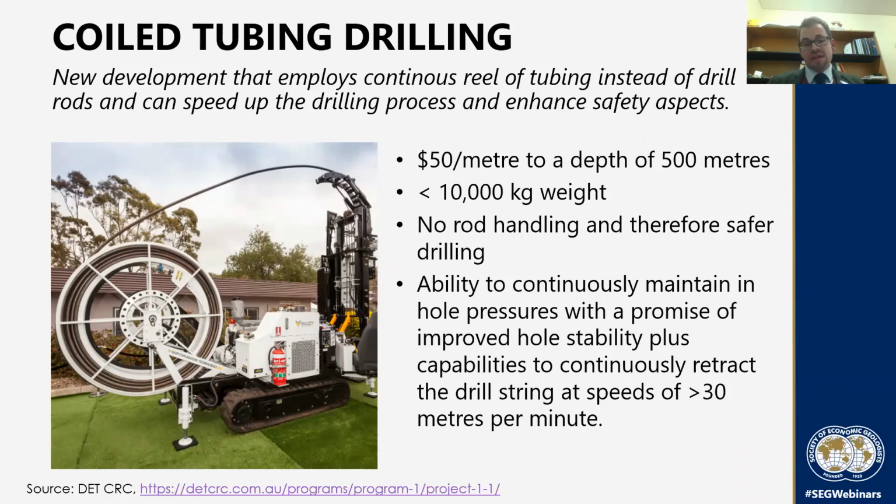I've myself never used this type of drilling because it's quite new and it's under R&D at the moment. However, what I read from that website is that the drilling cost is only $50 a meter down to a depth of 500 meters. Now that is comparably a really cheap tool to obtain a sample, especially given that diamond drilling is usually around $200 a meter.